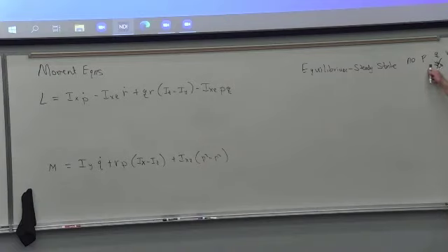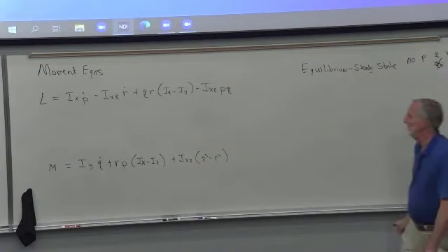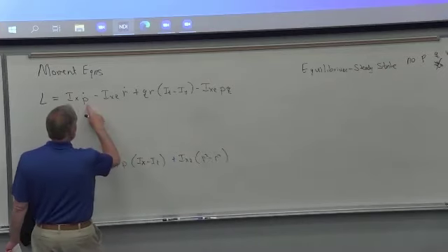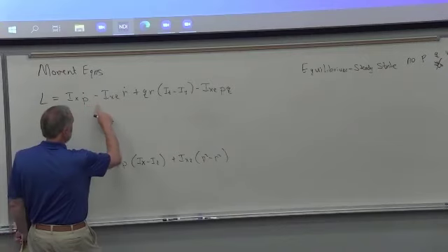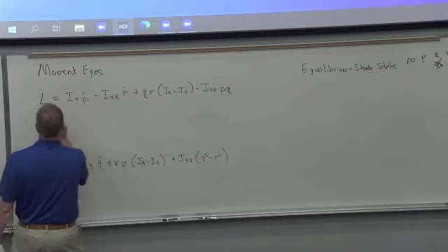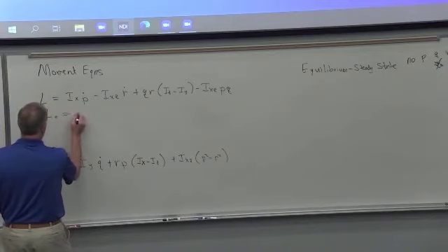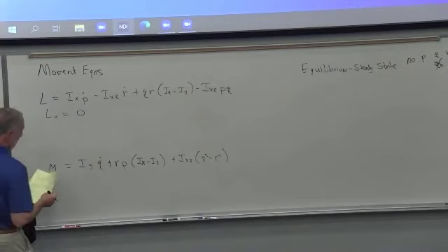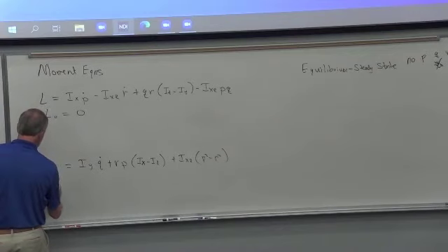So if all of the rates are 0, you can see that these equations become pretty simple. All right, there's no P in the steady state condition. There's no Q or R. So all of this stuff boils down to this. And then the same thing for the pitch rate.